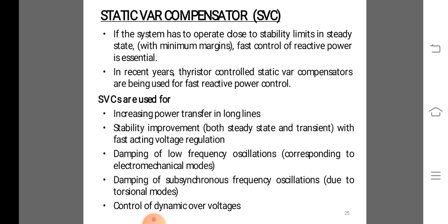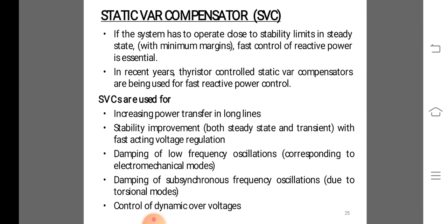In recent years, reactive compensation of charging power has been made feasible with the application of three-phase thyristor and power control circuits with automatic control function. The term static VAR compensator is applied to a number of static VAR compensation devices for use in shunt reactive control. These devices consist of shunt connected static reactive elements, that means linear or non-linear reactor and capacitor configured into